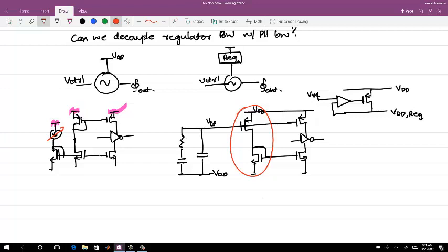So what decides the frequency of the oscillator? Okay, let me just ask you this. This is VH and this is V low. Given you size the inverter once, what decides the frequency of the oscillator? VH minus VM. Now, if you are using these MOSFETs as current sources, M0 and M1, what did you do? Initially the input supply was this, right? So how did you change the VH?